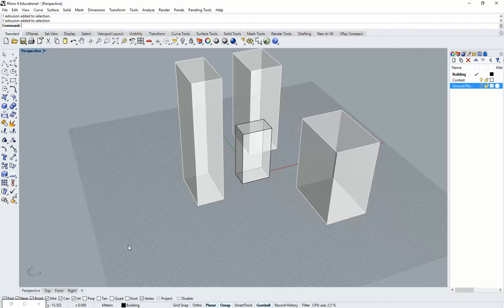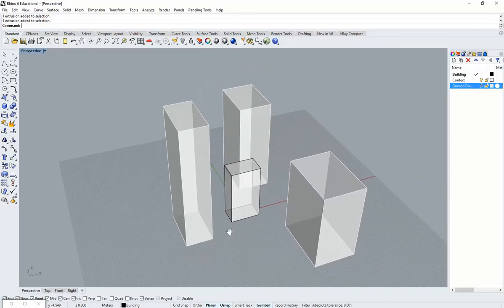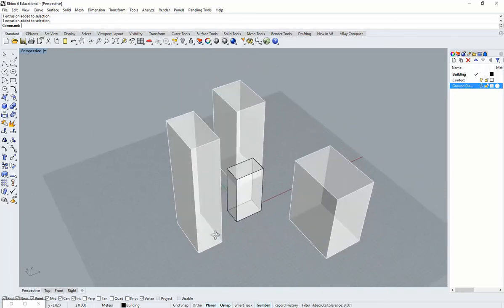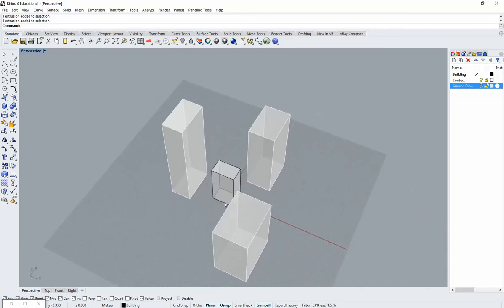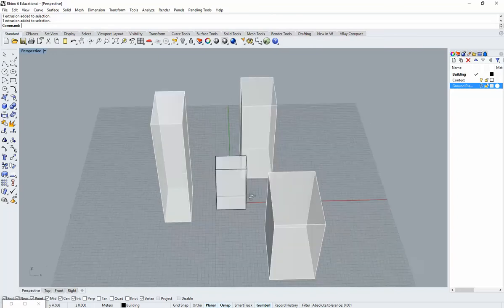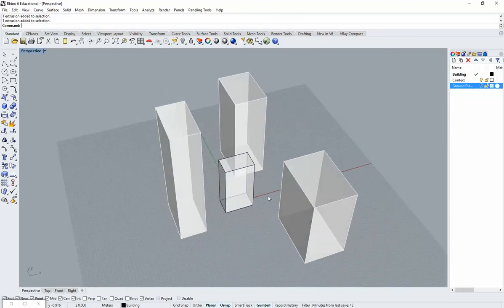The other thing is that I'm in meters, so you'll see that my units here are in meters. If I'm not mistaken, Ladybug will assume that your model is in meters, and if it finds that it's not, it will do a conversion for you. So it's best to convert your model to meters before you try these simulations and have it prepared so that when you're trying to visualize things, everything's at the right scale. Okay, let's get into it.